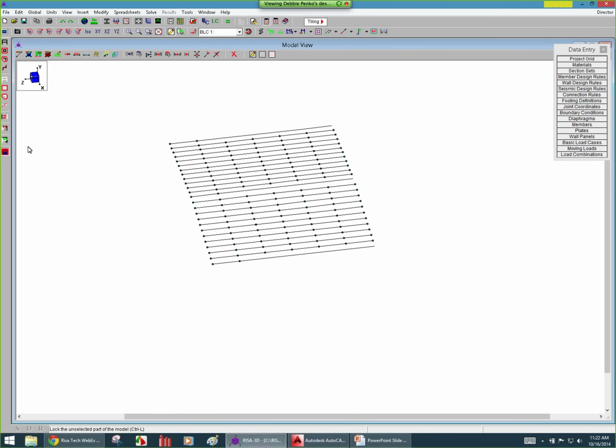One of the things to think about with those purlins is how you are going to actually connect them. Are they continuous? Are you lapping them in a way that you can say they're going to be a continuous member? It looks like people do this a variety of different ways, but you can probably consider them to be continuous. What that does mean, though, is are they really continuous when they connect to these back frames? Maybe they're continuous along the length of the member, but maybe not when you get back to this column and this last frame.